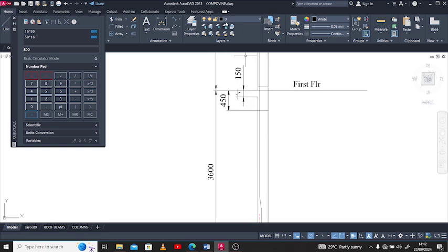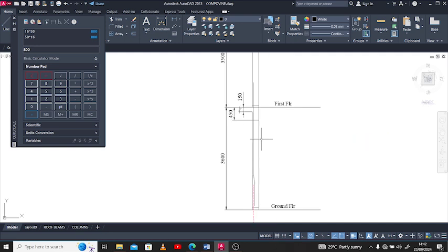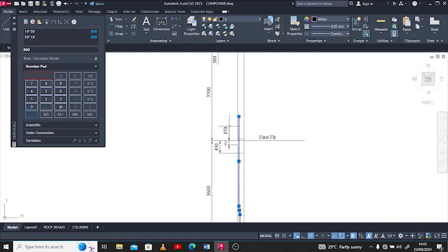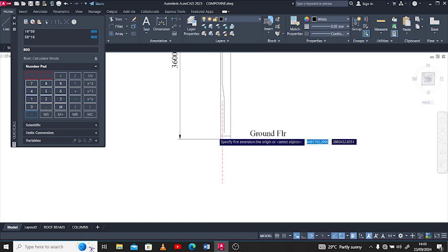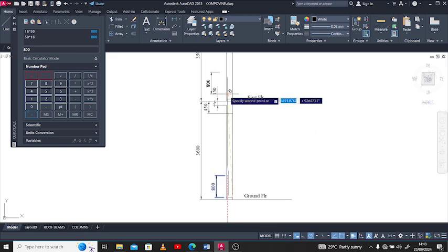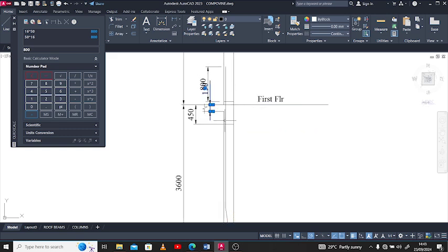You see that now? And do not forget, the cover to reinforcement for a column is a minimum of 40 mm. So you see that we have a minimum of 40 mm here, from the face of the concrete column. So we have a single bar spanning just this way, which laps at this point to connect the stress. And the lap length, as I showed you, is 50D from here to this place. You may want to match the properties. The same thing for the upper floor, where we have this also.